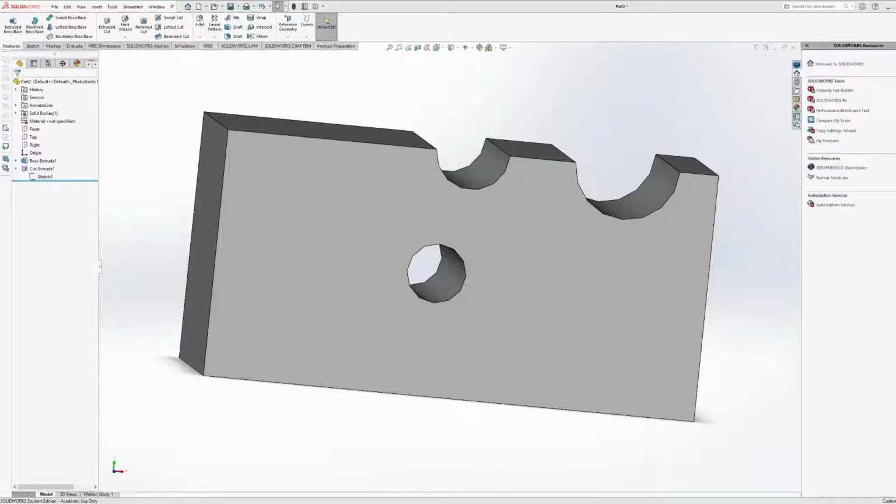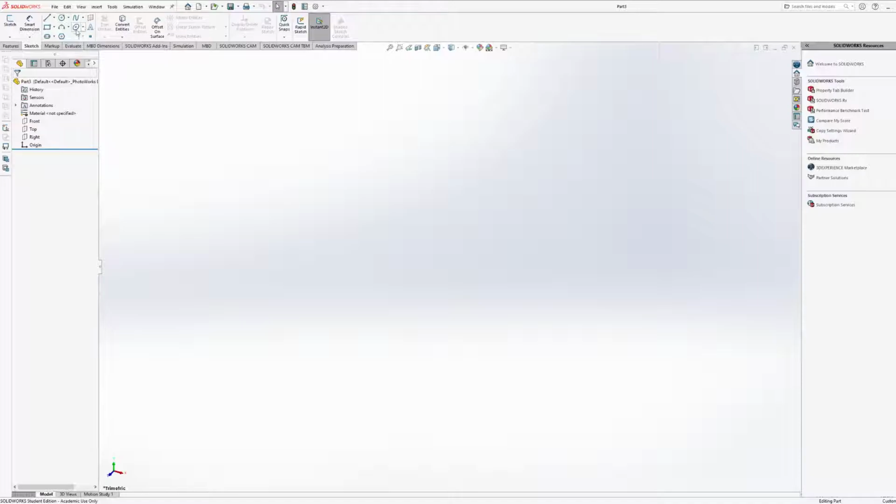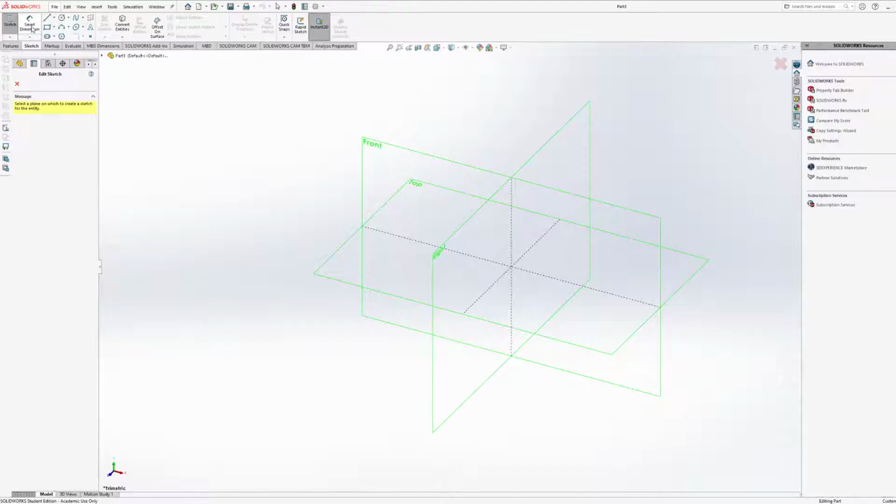Triangle sketch. Yeah, if you want to do something like that, I'm opening up so many parts, holy cow. It might be a little bit trickier. I don't think there's a specific sketch tool for it, just because there's so much more variation to it. But let's say you wanted to just make a basic triangle, or something that has a triangular profile. You're typically going to want your line tool. Either your line tool or your rectangle tool are probably going to be your best friends.